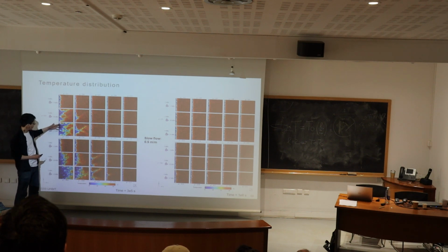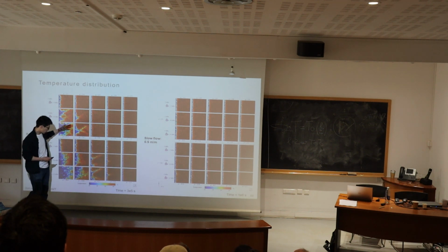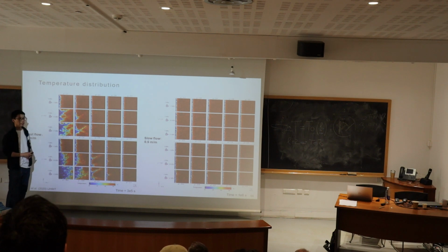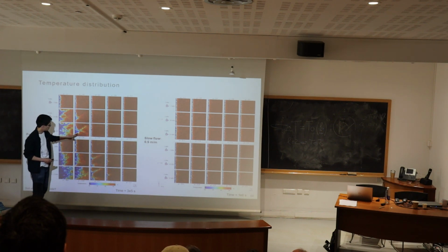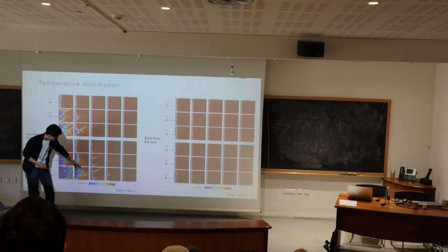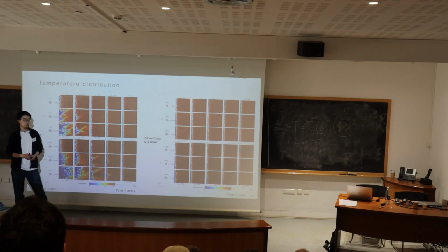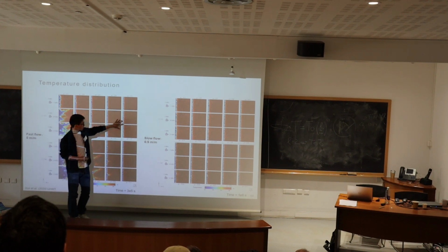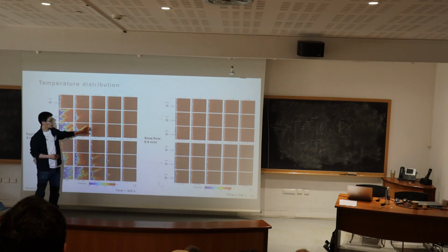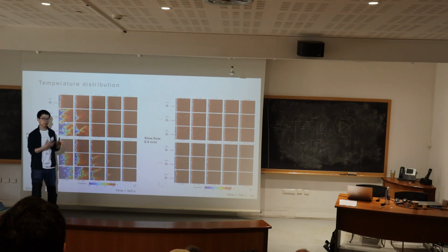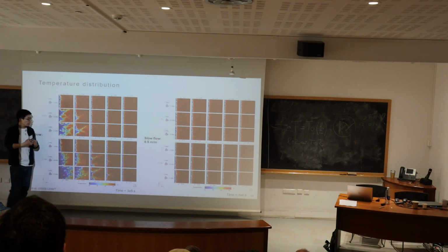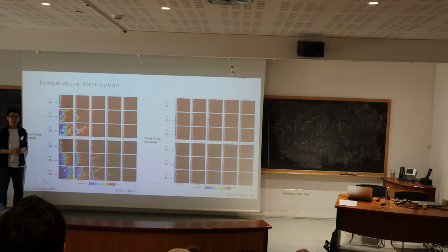So we see the temperature decrease significantly near these fractures. We see a clear coning effect, especially in some of the cases close to the percolation threshold, which is around 6. And the disconnected system is more dominated by heat conduction through the matrix, because the fractures can't play much role in the flow and therefore in the heat convection.